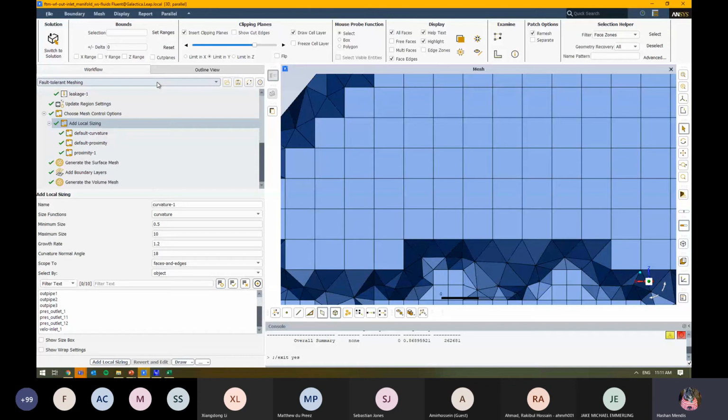No issues. So Stefan asks, if the surface mesh is not refined, can you create an erroneous location of flow separation? Yes, if you don't have enough refinement around some of your flow features, you can artificially create separation, and that could be because numerically you're diffusing what's happening in that situation. That's why it's important to do a mesh study. You want to make sure you're looking around those areas of interest and refining around those regions.